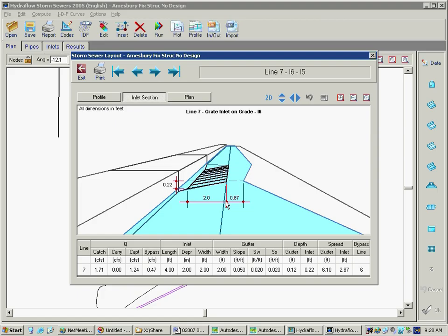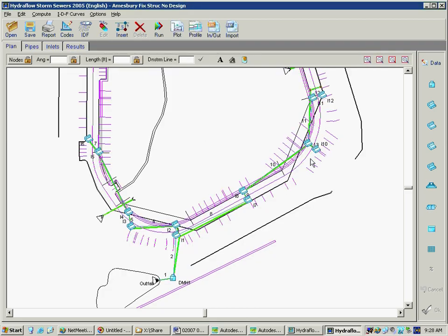And the last thing I had was the global edit feature when you're designing in plan view. If you go in and enter your Manning's n at .013, and then you discover that the ordinance lets you use .012, it may tip the balance in your favor if you're trying to get something to work. And you can go into the plan view and globally edit values.